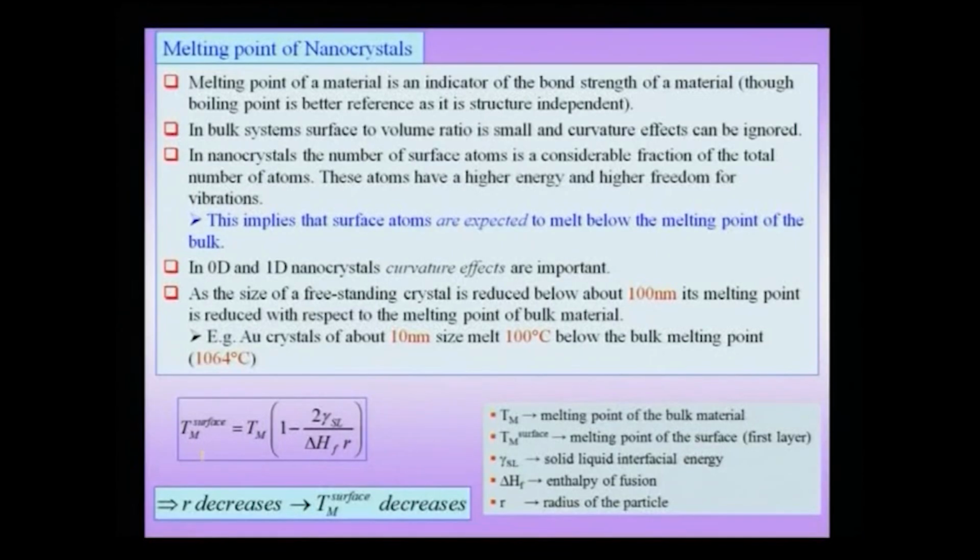After having a broad overview on phase transformation and the important concept of a critical radius for phase transformations, let us look at melting of nanocrystals. We had noted that we have a well defined melting point Tm at which the entire lattice breaks, and therefore you have a molten state, and this is unlike the freezing which we had talked about. On the other hand, when we talked about the melting point, it was the melting point of what is known as a bulk crystal or a large crystal.